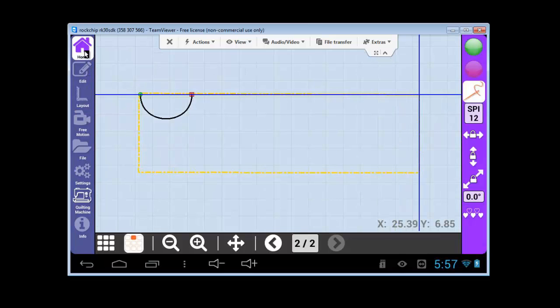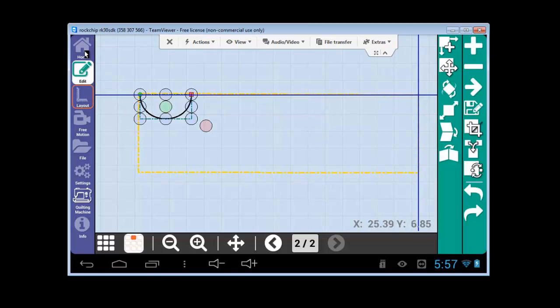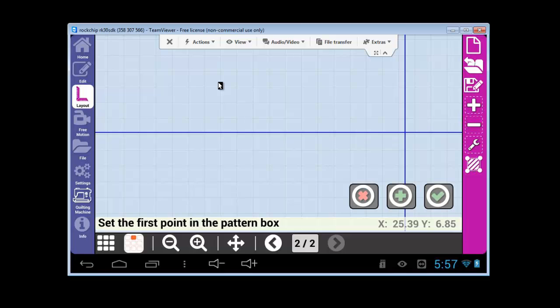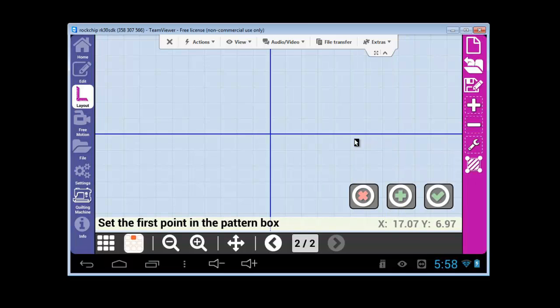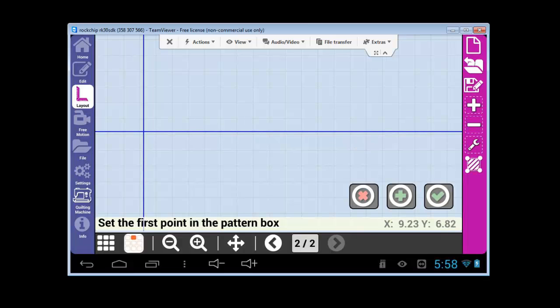And then, oh, sorry, go ahead. No, I was just going back to the wrench. I forgot the wrench. The wrench and the plus button both kind of do the same thing, right? They set the pattern boxes. More or less, but you just hit the wrench icon, so now you have to retrace this pattern box. Whatever pattern box you're currently looking at, it lets you redraw those dimensions. That's not necessarily creating a new pattern box. That's kind of changing the one you already have. That's correct. So we're going to have to redraw the one we just had selected, because it's gone now. So let's hurry up and we'll just draw a quick rectangle here. Okay. I can do that. You're almost a pro.